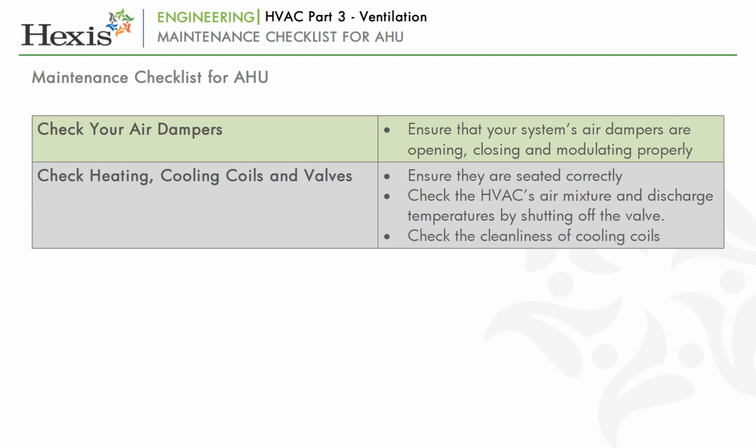To check the cooling coils, you'll need to check their cleanliness. If they are covered in dirt, dust and debris, wipe them down with a clean cloth. Dirty coils increase static air pressure, causing increased fan energy waste. More air is needed to flow over a dirty cooling coil in order to elicit the same heating and cooling effects.